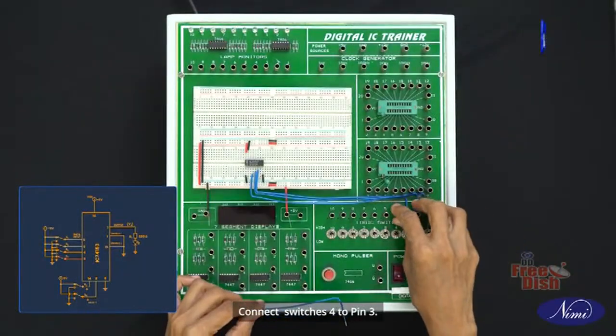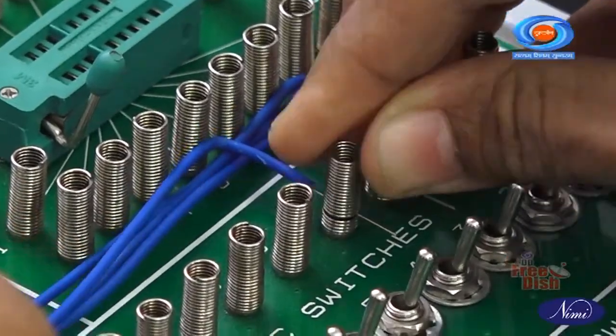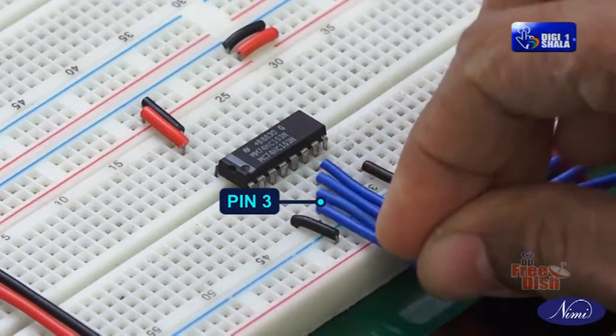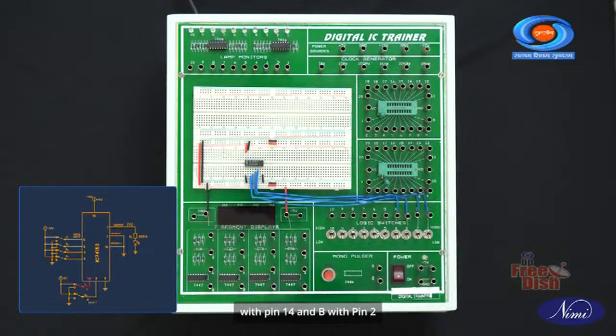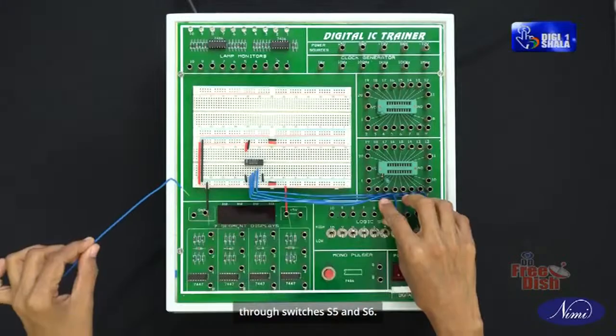Connect switch 4 to pin 3. Connect the selection input A with pin 14 and B with pin 2 through switches S5 and S6.